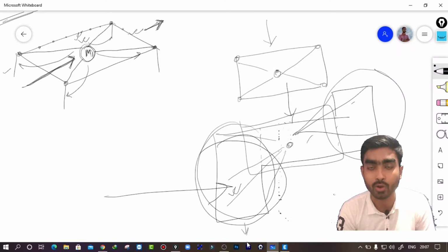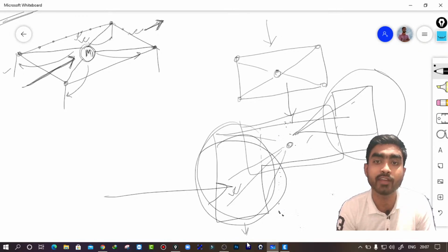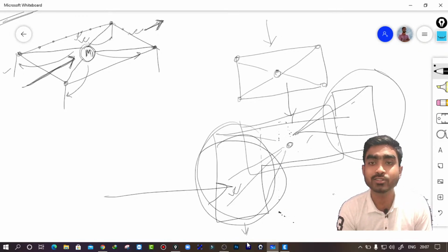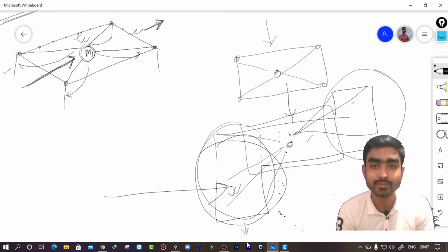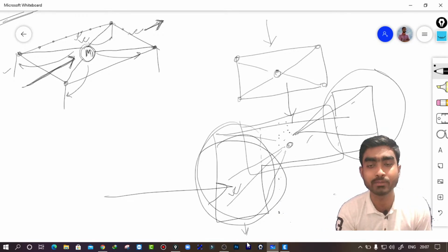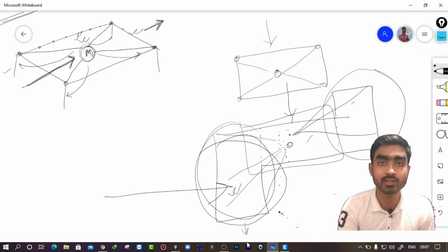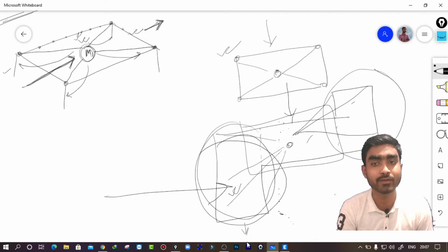There is nothing wrong, because the semi-rigid diaphragm is the actual or proper behavior, you can say. Just to reduce the time consumed by the analysis process, or just to make the process simple, what we used to do is provide rigid diaphragms in the regular structures, and in the irregular structures we used to provide the semi-rigid diaphragm.